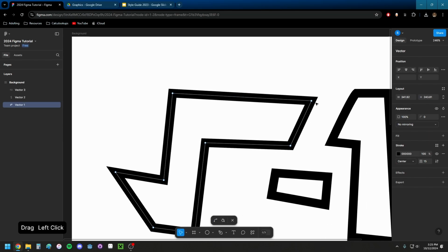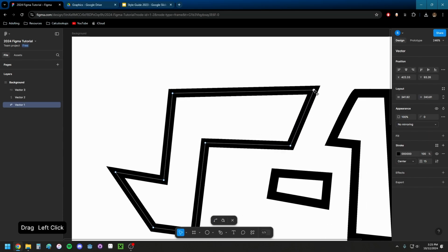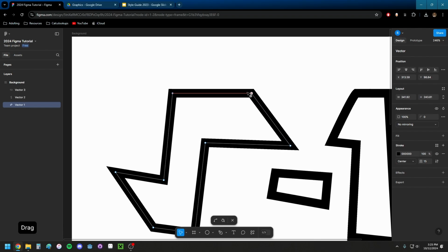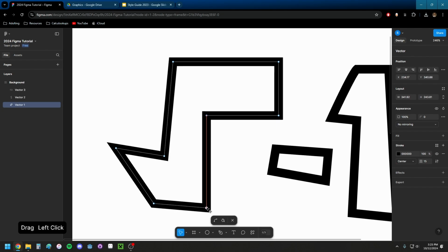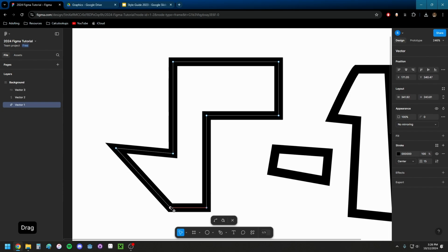We want everything to be all trued up. So we're going to double click, go into Node Editor, and we can come up here, wait till this is red. Boom. Now this upper segment right here, this one's flat. Excellent. We just want to keep doing that. Right now I'm just going to block it out, make sure everything's flat and square with itself. And I want to true this point up with this one, so it's both going to be flat and in line. There it is. Make this one flat. Make these roughly the same length.